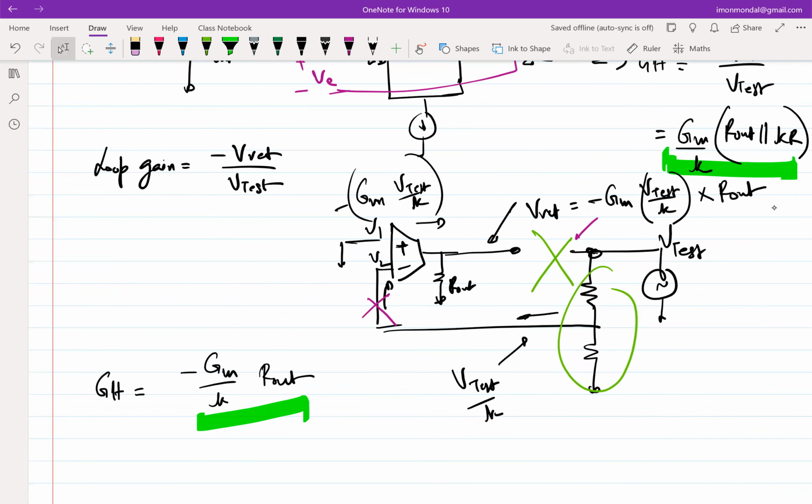Okay. In the problematic case where we are breaking, this stack of resistances was drawing current, right? So now if you break, you are disturbing the quiescent operation of the circuit, because it was supposed to load current under natural conditions, which it doesn't, because you took away the loader, right? So if you have to restore it, you'll have to put it back at the other side of your breakpoint. In principle this is pretty simple to do, but it requires a bit more analysis. So we'll not go there.